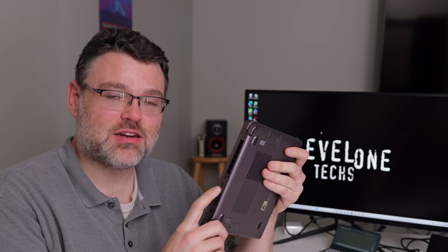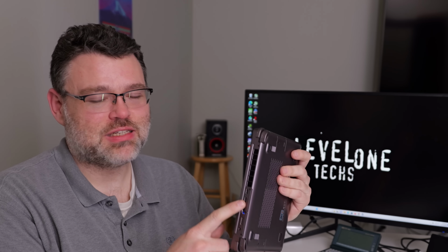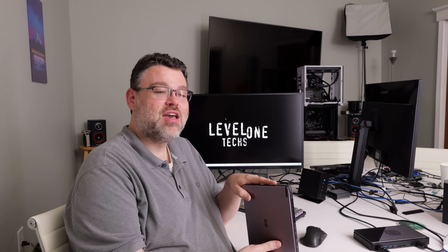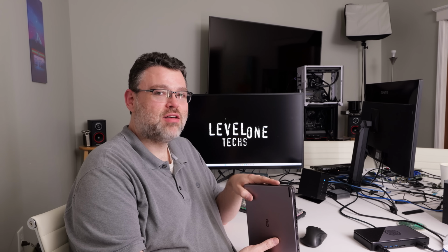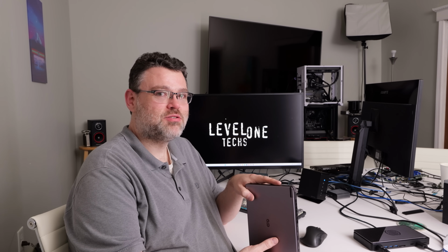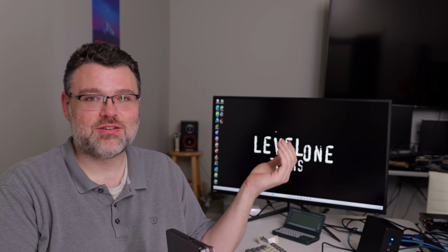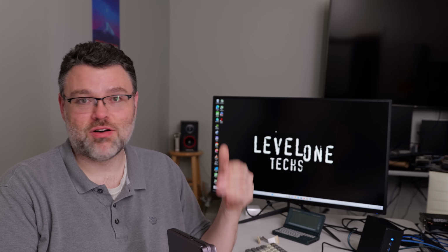A lot of these USB-C connectors start at 10,000 insertions and go up to like 100,000, 500,000 insertions. If you have a cell phone with a Type-C connection and you plug it in to charge every day, you can definitely vouch for the fact that, wow, these connectors seem to be rated for only a couple of hundred insertions. It depends on which vendor and which model you get and how thick the gold plating is. There's a lot that goes into it.